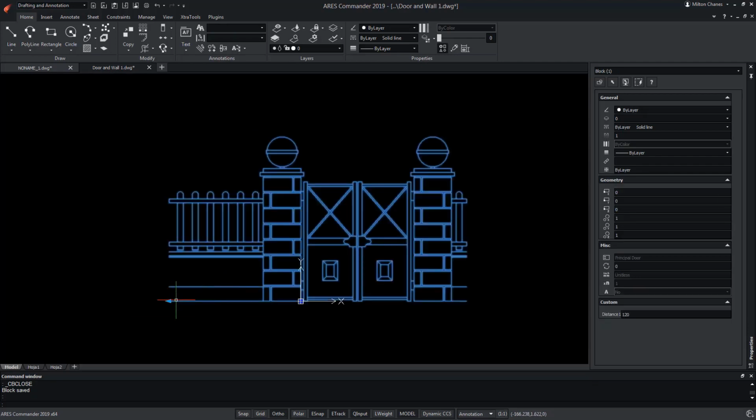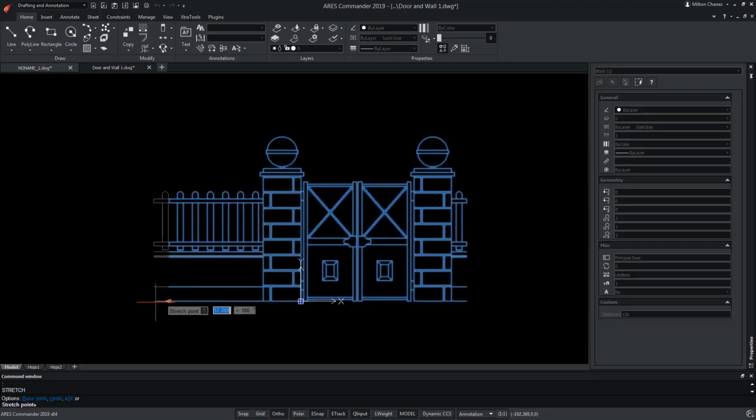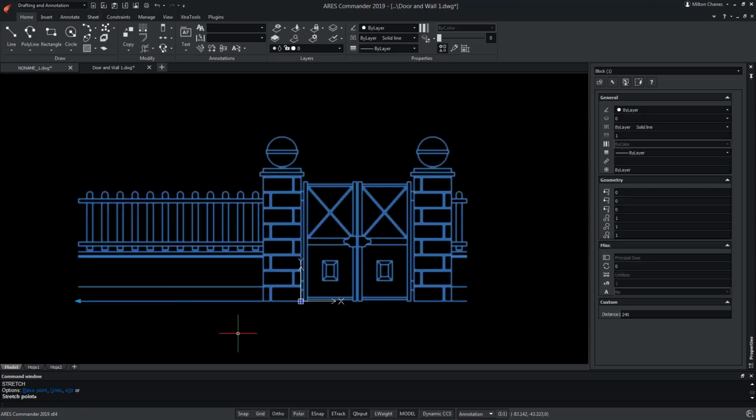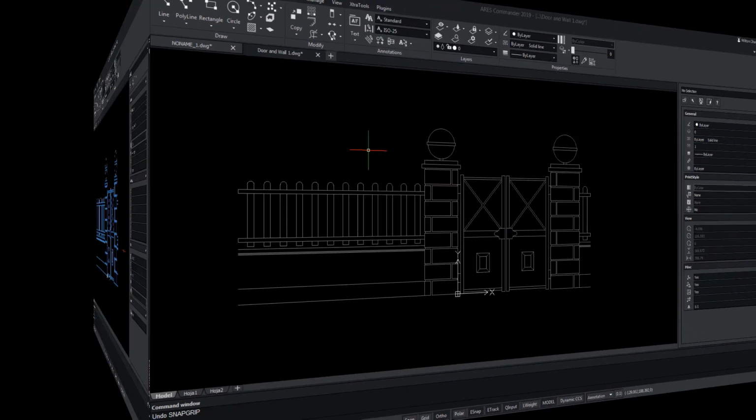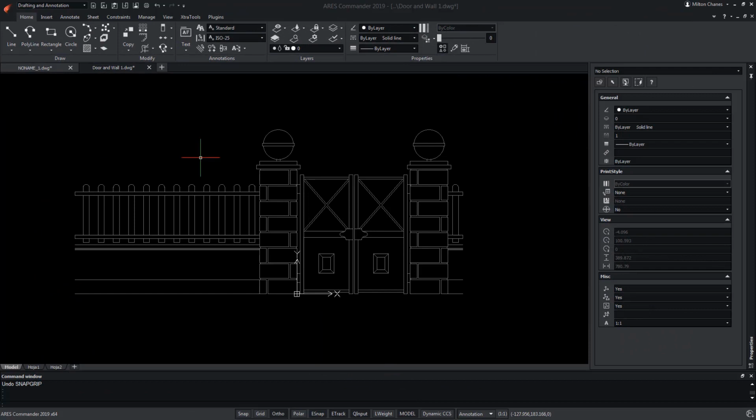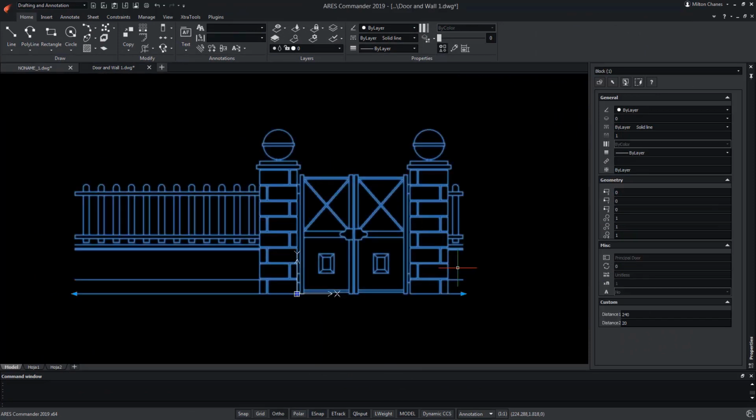Now, when moving the grip, we will see that its movement will respect the increase that we've granted. In this way, we ensure that exact pieces enter. This same operation can be done on the opposite side of the block, so we can stretch it to the right side too. After doing the operations on the opposite side, we can also create a fence in the other direction.